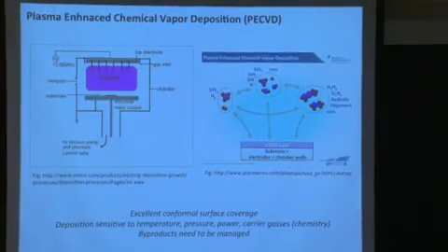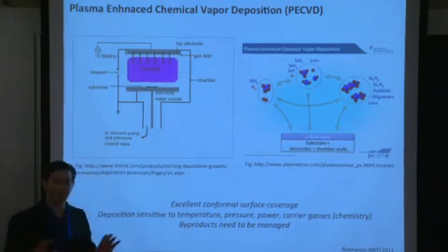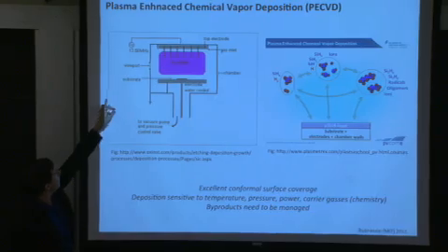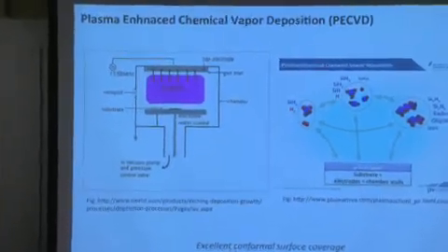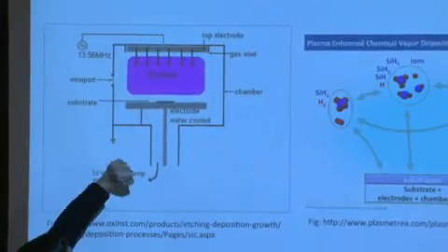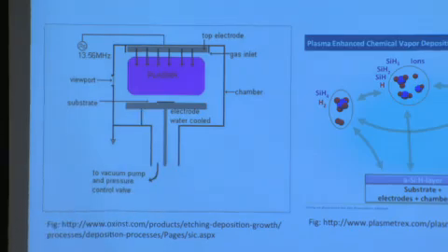What is the active molecule that's being accelerated and deposited on the surface? And usually it's some probability distribution function of various species. We have the plasmas created by this radio frequency, or let's put it this way, usually you have a plasma frequency of around 13.56 megahertz. Does anybody know why this 13.56 keeps on coming up over and over again? Yeah? The energy to ionize hydrogen, right?